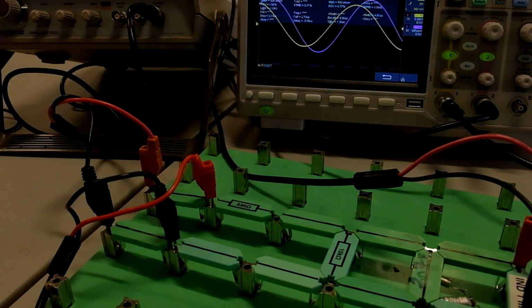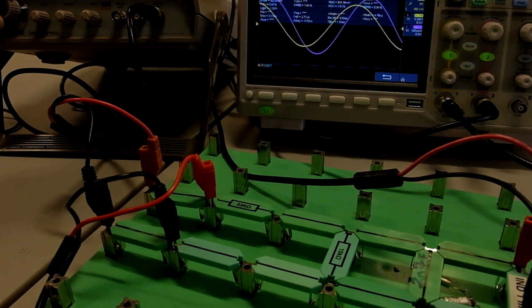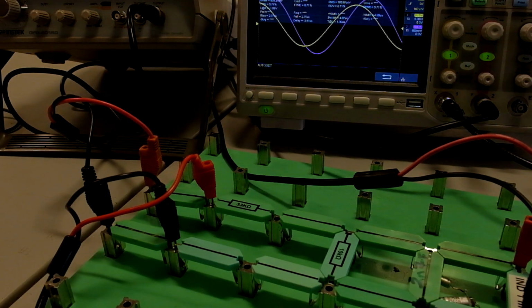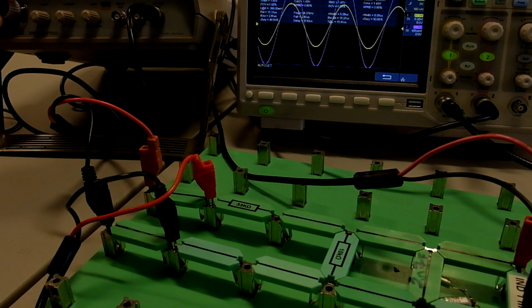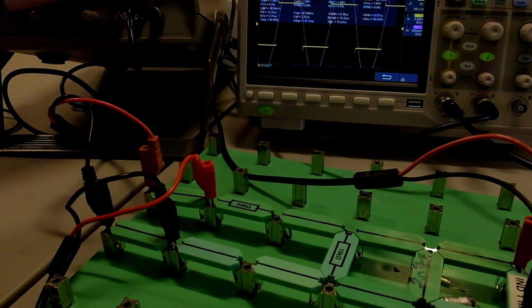and we've proved that by experiment. This circuit is also a bandpass filter. At the moment we've got a sine wave going in. We'll just adjust the time base to see more. We've got a sine wave going in. If we go back to resonance, and we change the input voltage to a square wave, we still get a sine wave coming out. So why would you have a square wave going in but just a sine wave coming out?